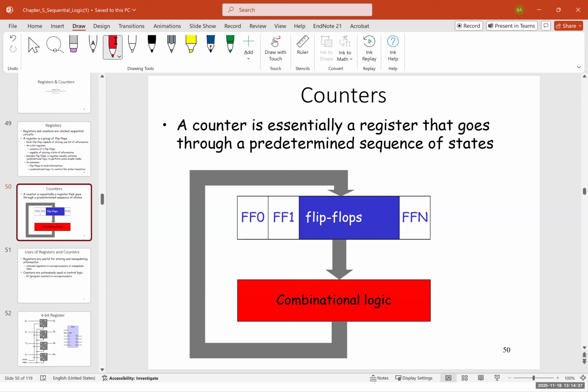So the most basic part of any counter is going to be its memory, okay? If you don't have any memory, you don't have anything to add to on top of. So usually, a flip-flop with a combinational logic circuit, which is usually an adder, you can have a full adder and add 1 to it, and then save it again in the same flip-flop. So imagine you have a full adder or a half adder. I'm just going to put a full adder, which is combinational, and I add 1 to it.